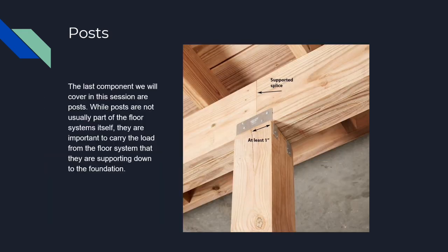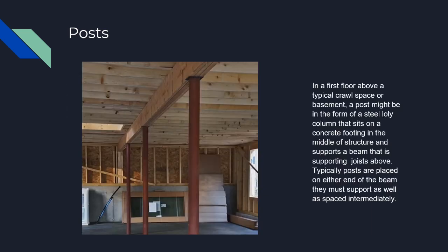The last component we will cover in this session are posts. While posts are not usually part of the floor system itself, they are important to carry the load from the floor system that they are supporting down to the foundation. In a first floor, in a typical crawl space or basement, a post might be in the form of a steel lolly column that sits on a concrete footing in the middle of the structure and supports a beam that is supporting the joist above.